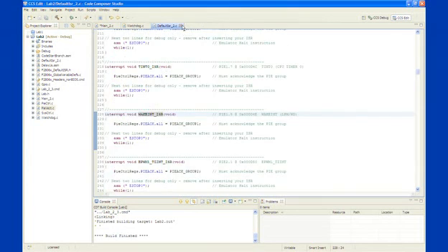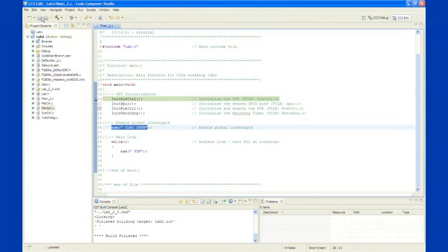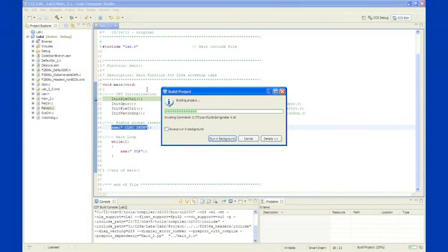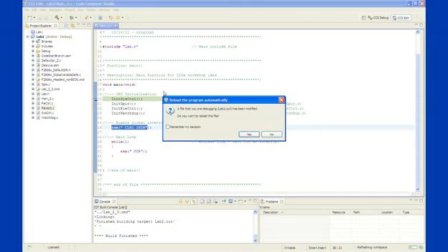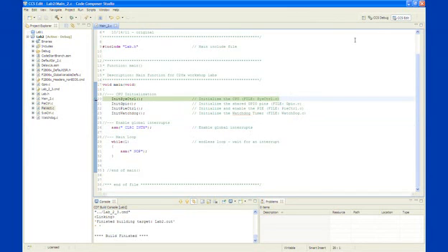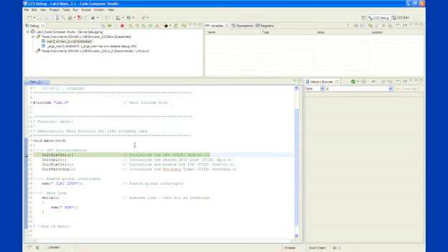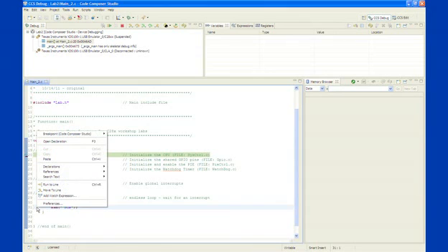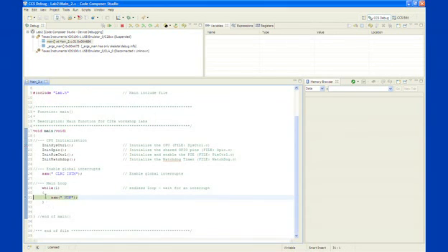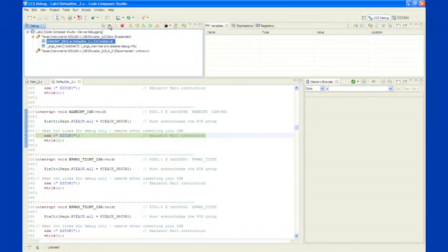All right, let's close out these files here. And what I'm going to do is I'm going to rebuild this. And then we're going to load the program automatically. Switch back to CCS debug. Once again, run to line in our main loop. And this time I'm going to run it, and if all goes well, we should have the watchdog generate an interrupt, and we will be trapped in our interrupt service routine, which we are right here at 1.8.